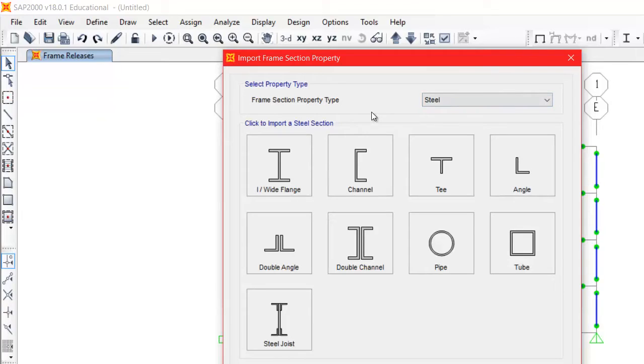If you want to define a new material, because this steel that's defined here has some parameters like E, Fy, and so on. If you want to modify those things, which for your assignment you for sure need to, because you have your own material now, then you can define a new material. You call it like steel A992 or something, and then you start defining E and Fy and any other parameters that you will need. So I'll just stick with steel for now.